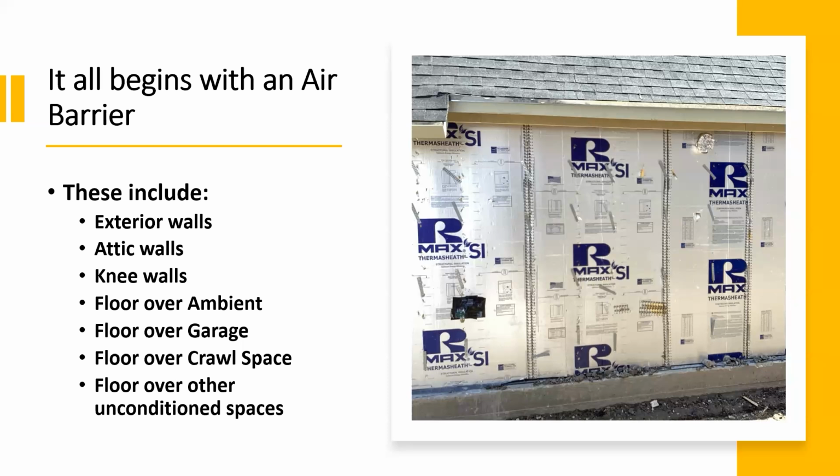So with the air barrier, it's not just including the exterior wall. We talked about the garage wall, but also when you're doing the inspections, you need to determine what's the separation from conditioned and unconditioned. It's not just the outside. It can also be attic wall, knee walls, floor over ambient, floor over garage, floor over crawl space, and floor over all other unconditioned spaces.